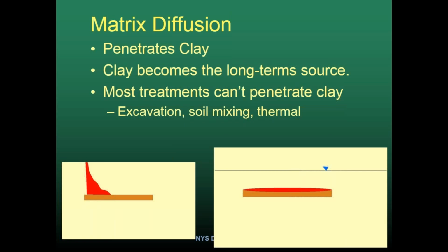You can still excavate. That always works. You can get chemical oxidant in contact with that contamination if you mix the soil, and the in situ thermal remedies will be effective too. The thermal remedies are expensive. They're also disruptive to the site, you have to put heating wells in a fairly tight spacing, but they absolutely do work. And if you need to have the site cleaned up quickly with a guaranteed result, the thermal remedies certainly have carved out a niche for themselves.